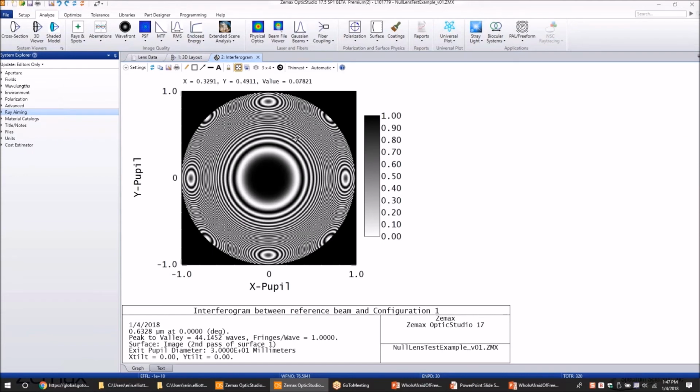So these rings in the interferometer get much closer together. And what we see is that out here, I'm getting aliasing. It's instantly evident that I've got an aliased pattern here. If your interferometer doesn't contain enough pixels, you can easily get into this situation. This part cannot be tested accurately just using this interferometer test. So we need to help it a little bit.